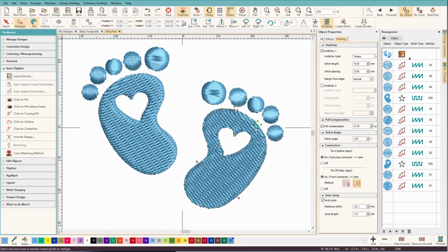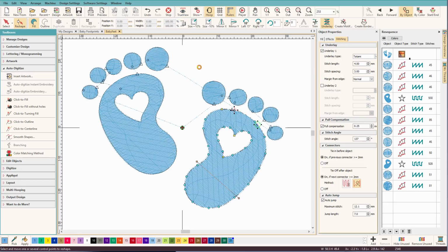Now, one thing I'd like to point out is, can you see these little dots? Well, let's turn off True View. And to toggle that off, that's just T. See, T on, T off. And you can see all these little dots around the shape. These are nodes, and these define the shape. So this software does a pretty good job of not putting too many nodes around here, because when you draw a shape, the ideal thing is to use the minimum number of nodes.